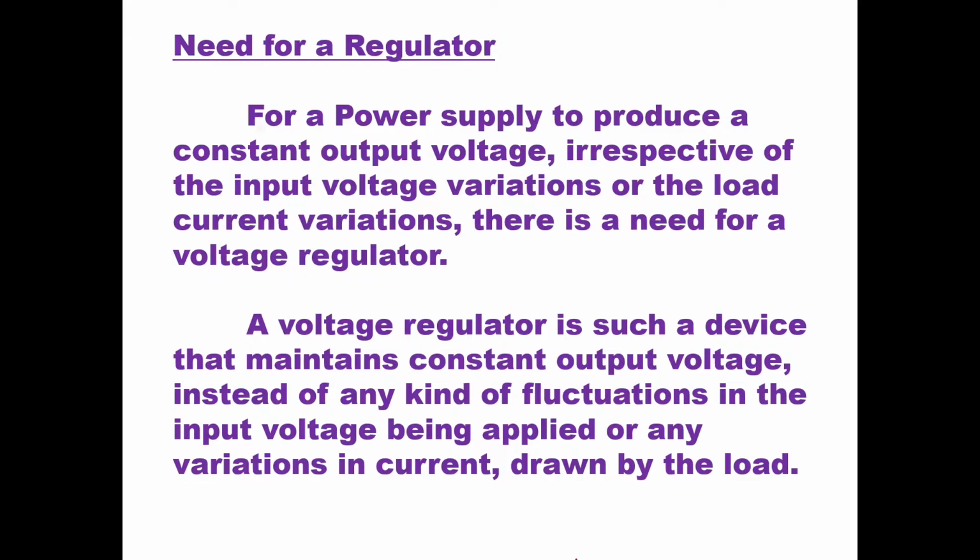Why do we need a regulator? Now, if we don't use a regulator, what happens? If we don't use a regulator, if the input varies, the output also varies. If the load varies, the output also varies. This is with respect to power supply we are speaking. That is why we require a regulator.